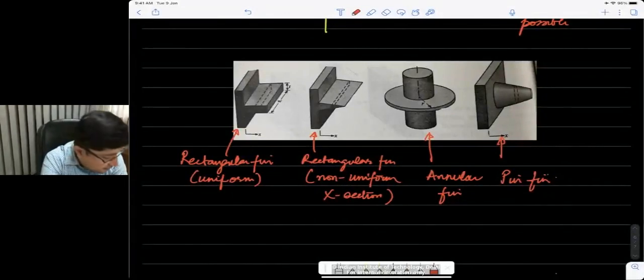What you're saying will work if whatever material you're adding in the form of a fin had an infinite thermal conductivity, because then the temperature would not drop along the fin and you would spread out the heat suddenly.